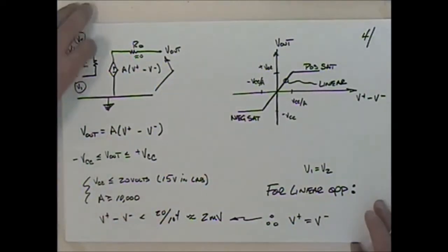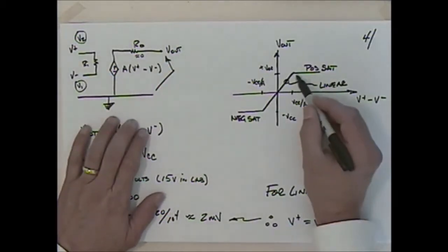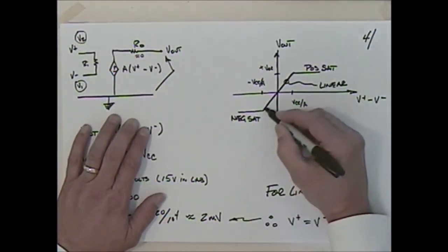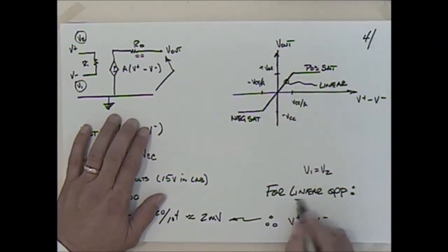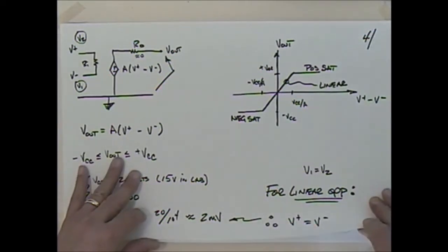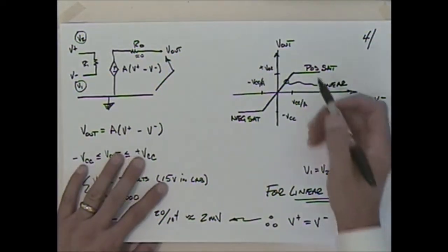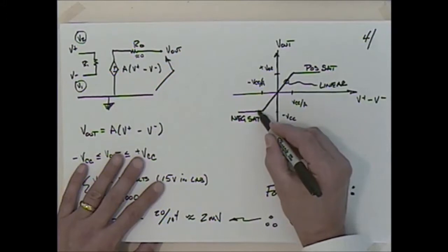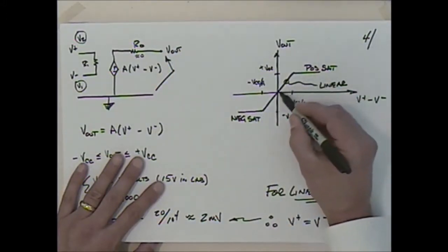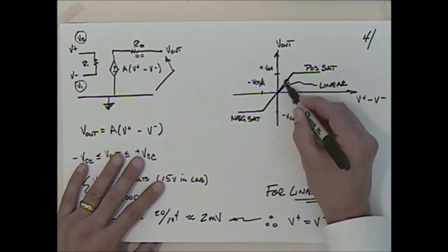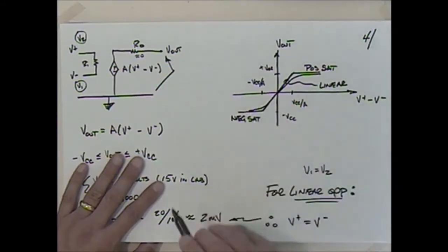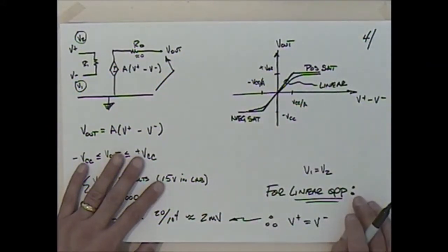And for our purpose in here, again, the electricals are going to go a lot further along and talk about what happens when you get into saturation. We're going to concentrate strictly in the linear region. So we're always going to use linear operation. That's going to make our life a lot easier. The last thing to mention here is nature tends not to like these nice corners like this. This looks good on the graph, but when we go into lab, one of the things you're going to do is build a saturation curve, and you'll probably find that your saturation curve has a little bit of roll-off like that, which is actually fine.